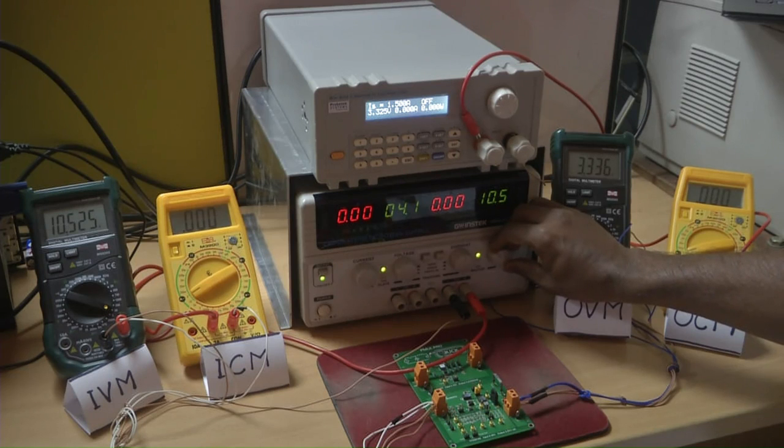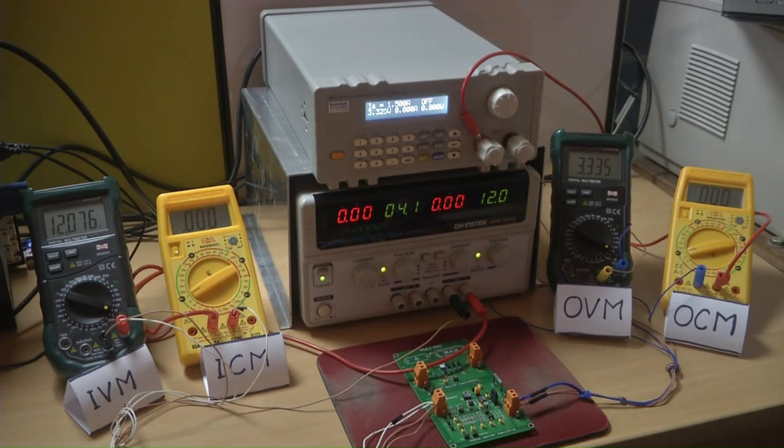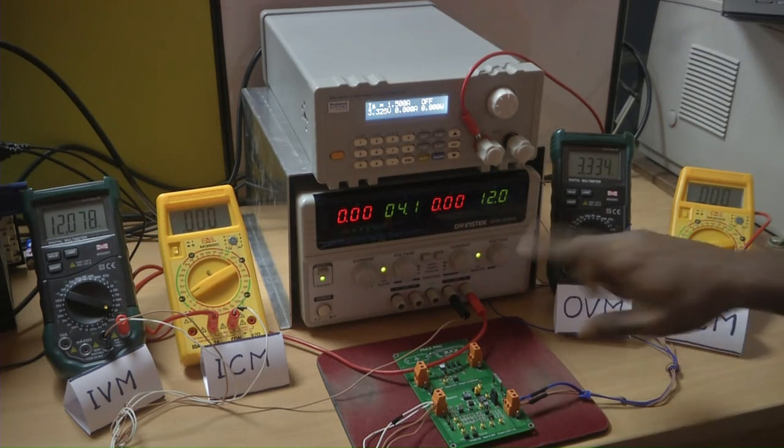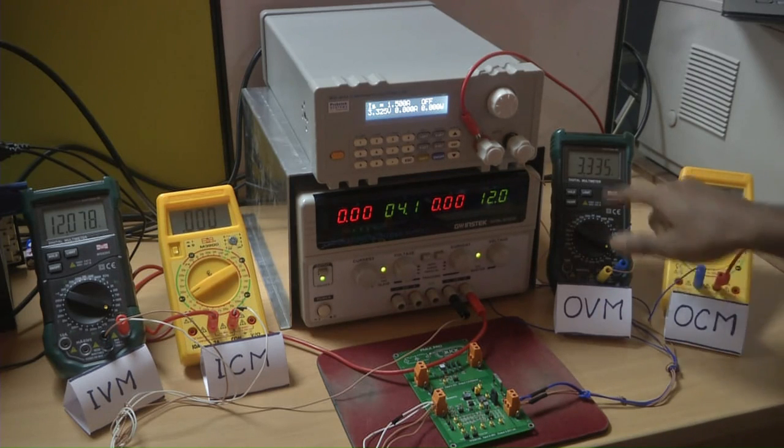So now you can see that we are showing you an input of 10 volts, and, no, actually step 2 should be 12 volts. Yes, the input is set at 12 volts, and as I was mentioning, 18, 24, 30 for 250 kilohertz, and then again 6, 12, 18, 24, 30 for 500 kilohertz.